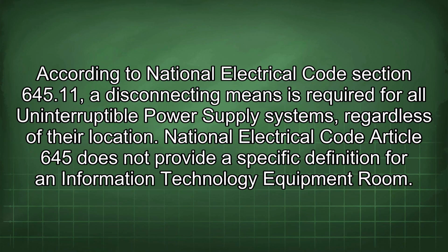According to National Electrical Code Section 645.11, a disconnecting means is required for all uninterruptible power supply systems, regardless of their location. National Electrical Code Article 645 does not provide a specific definition for an information technology equipment room.